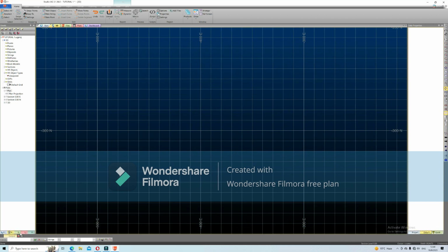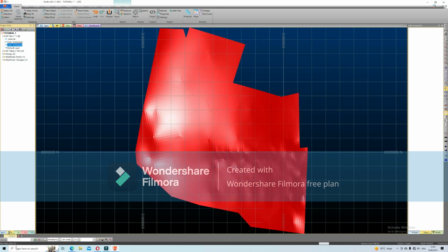The first thing that I'm going to do, I'm going to go to the project files here. Then I expand the ore files bar to load the ore body wireframe. So I drag and drop the ore body TR file, which is the wireframe. Then the PT file is the point file. It displays points for the ore body. Then I click here on sheets to remove the grid so that I can clearly visualize my ore body.